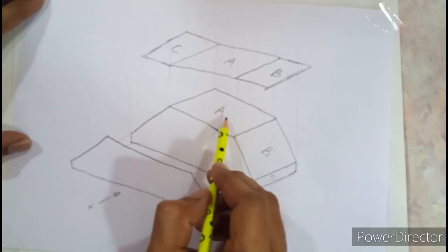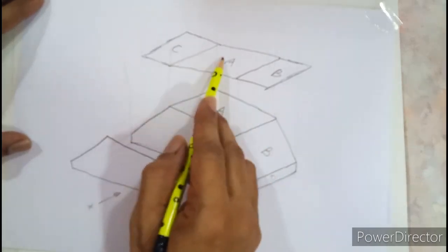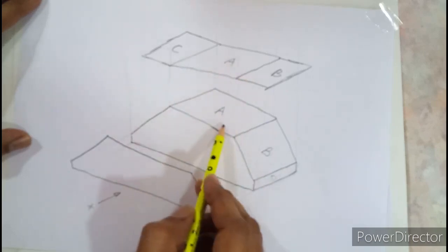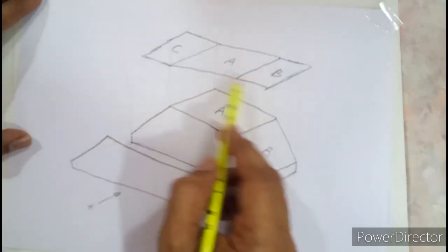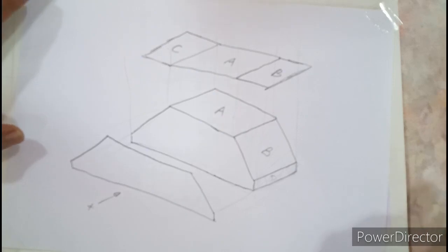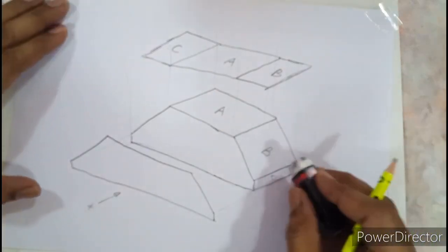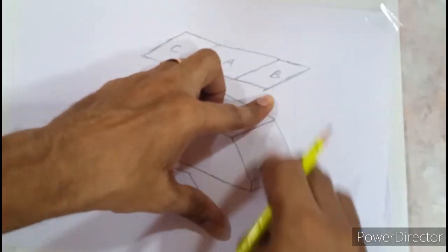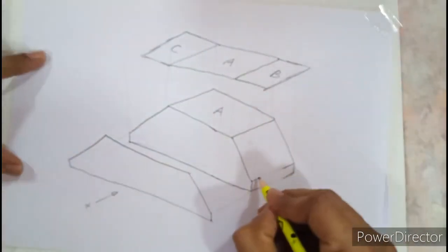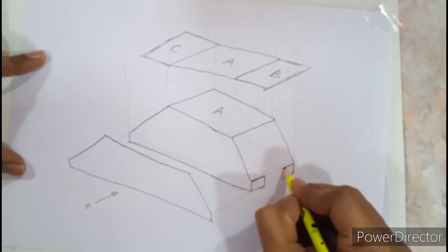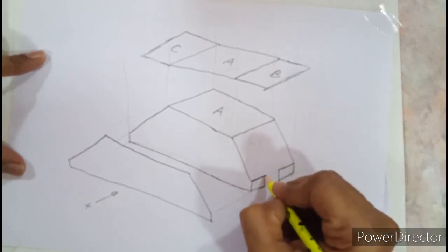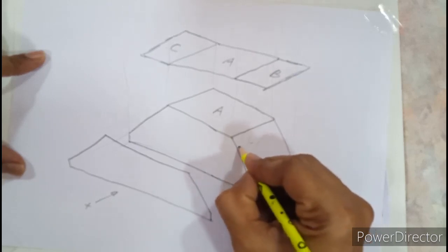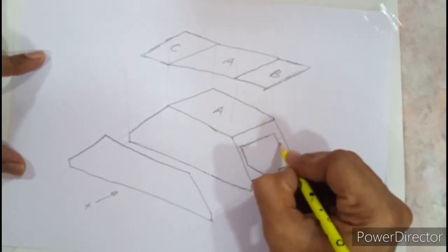So that is how you can see three different surfaces in the top view, where A is of the true length, true means exact length, whereas B and C are apparent length, which means reduced length. Now an important thing that needs to be discussed is, suppose within this platform, if you make some sort of cavity like this, let us cut the platform,